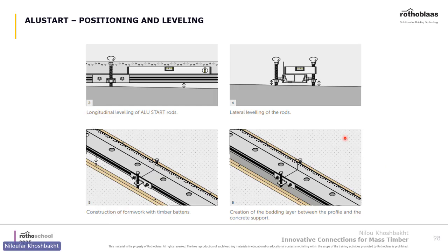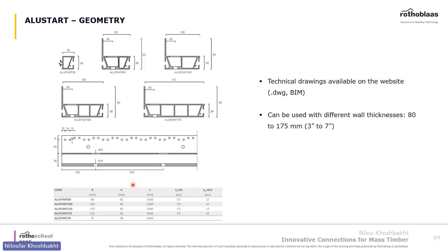And as you know, the concrete foundation is never level. The tolerances are in centimeters, and AluStart can help with that to adjust the level. And then after adjustment, you can put formwork and pour grout to level under the AluStart.